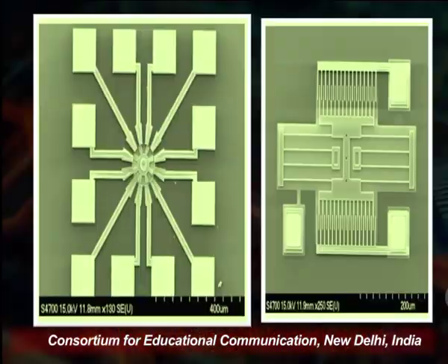So, this type of surface micromachining process is used to fabricate the analog devices integrated with MEMS accelerometer devices used for crash airbag deployment, and moreover there are two surface micromachined polysilicon devices. Here you see the SEM images of the devices deposited on the surface, and that is further used at the micro or the nano level.